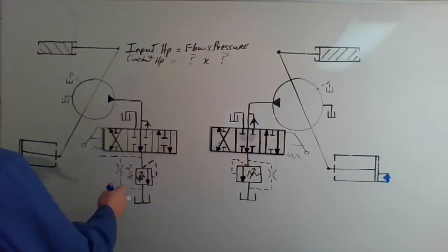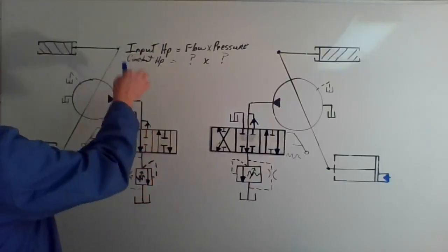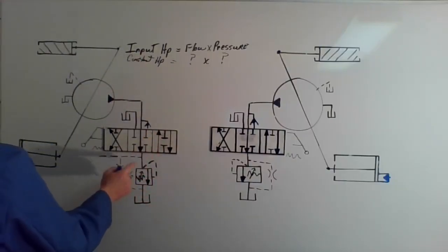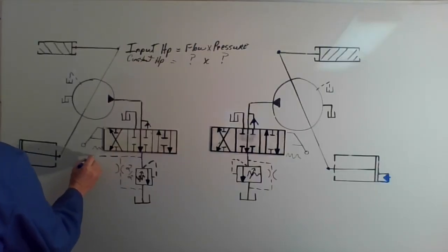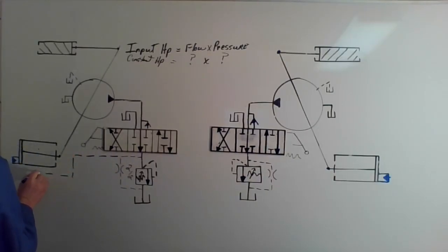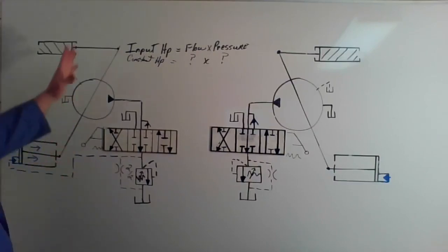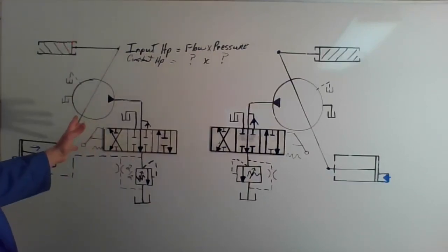So this is my negative flow control valve, and in neutral standby we can say there's going to be, well, probably 200 psi there, and I can take that pressure and send it over to physically de-stroke this particular pump.